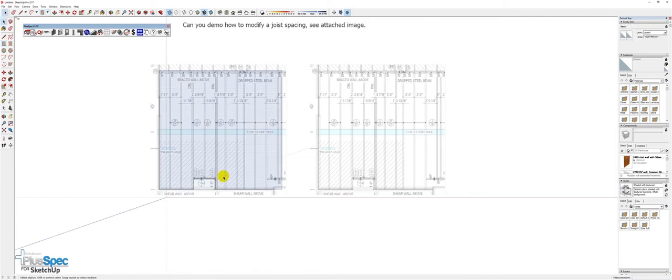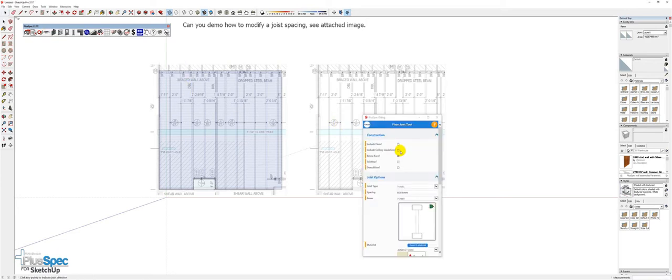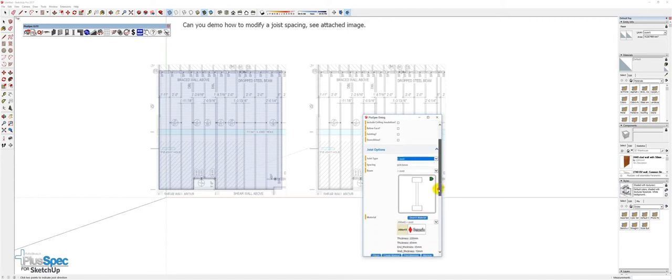Okay, first things first, the first one I'm just going to quickly go in and throw all the joists in at 600 centers, which is 2 feet, sorry. And so I'm just going to go to my joist tool and open it up, and these are just below face. Do I want to include a floor or not? I'm going to go above face, obviously deselecting below face. Choose the type of joist you want to do. I'm just going to use I-joist in this particular option.